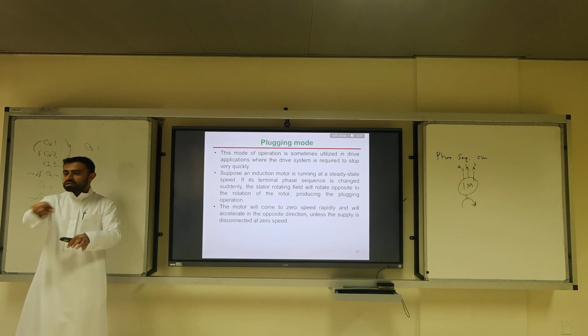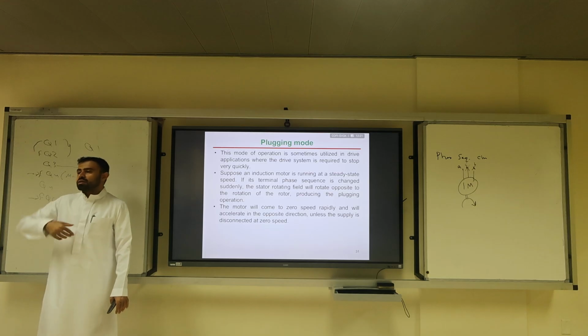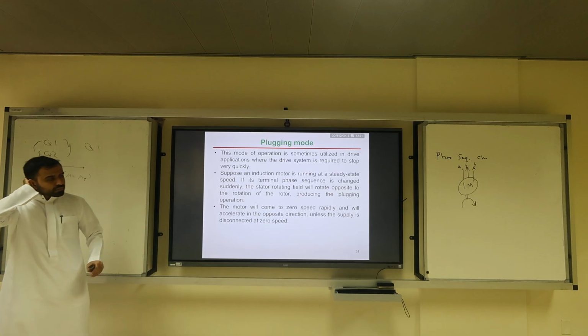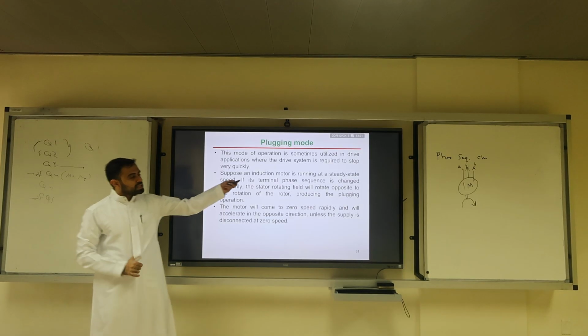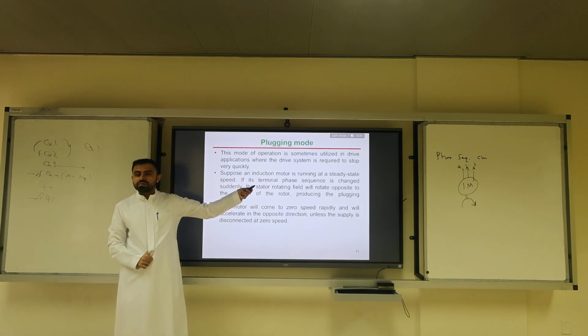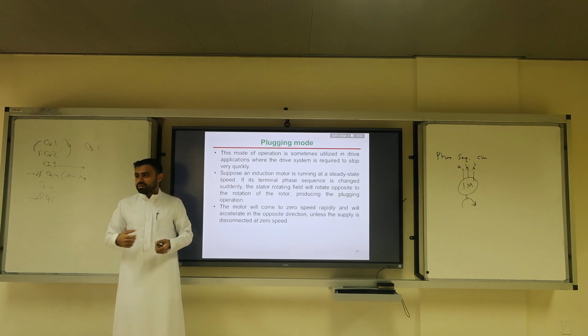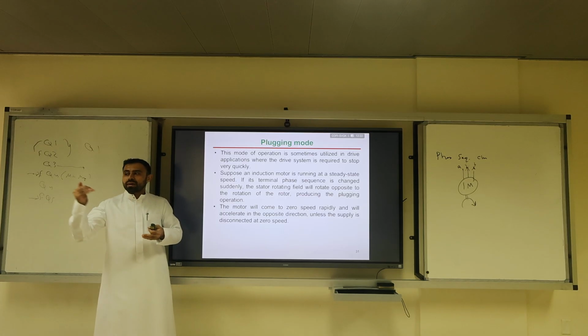So you just change the sequence of the firing signals, and then you connect C before that cable instead of B. So you do the phase sequence by means of power electronics. You don't do it by physical wiring, because you cannot change the wires if you're driving the car. That's not logical.